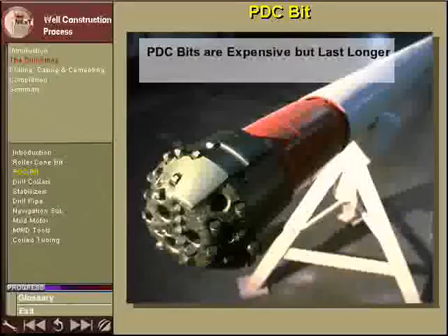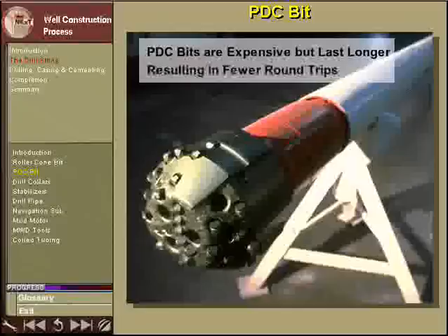PDC bits are expensive, but they last much longer than roller cone bits and can be used for long bit runs. This results in smaller numbers of round trips, and so the high cost of the bit is more than offset against the rig cost for tripping.